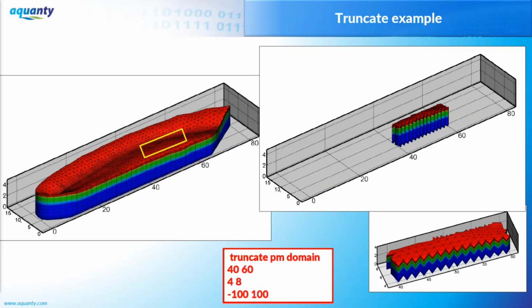At that point, if you wanted to immediately truncate the model results, you wouldn't be able to because the plot control file won't be available. So you'll just quickly run hsplot.exe, and then you can immediately terminate hsplot before it finishes. For example, if you have a very large model and hsplot takes a long time to run, just quickly run hsplot and then quit it.